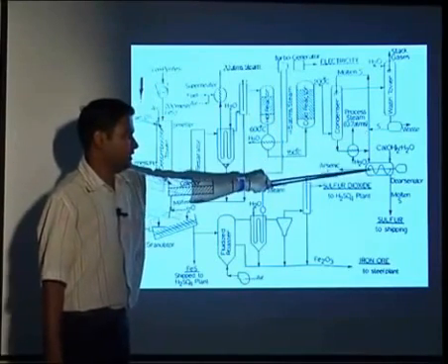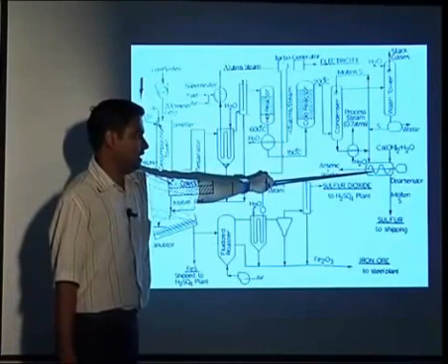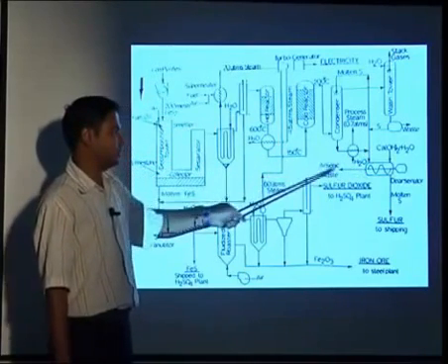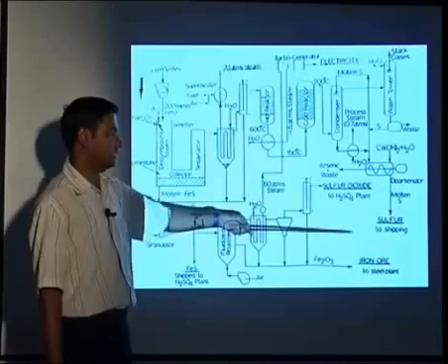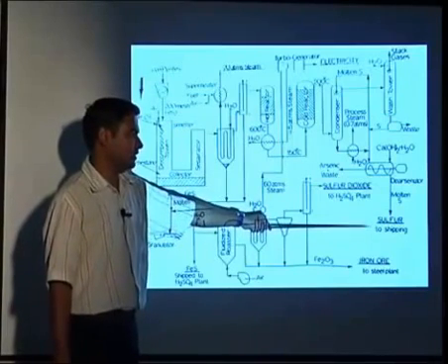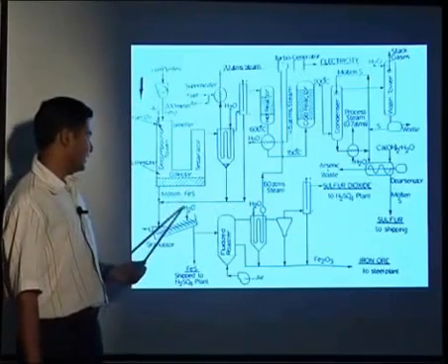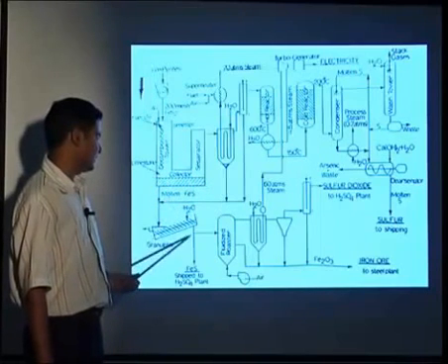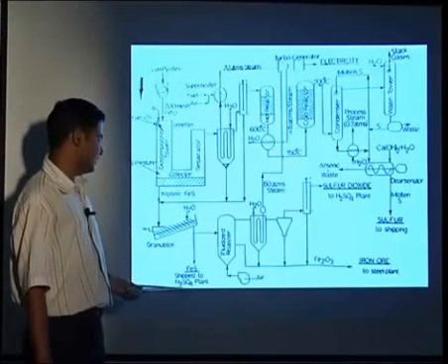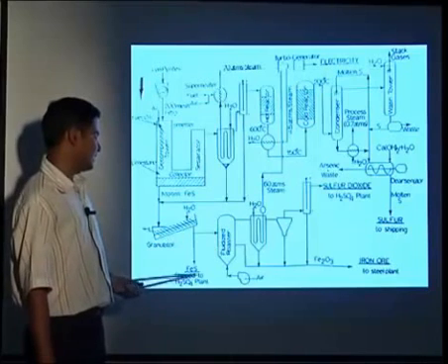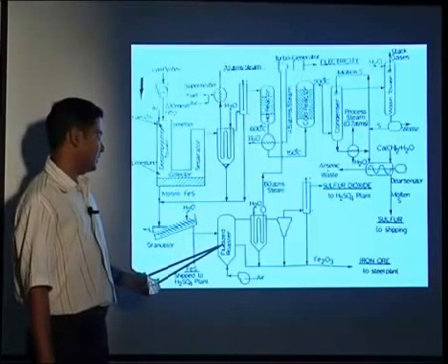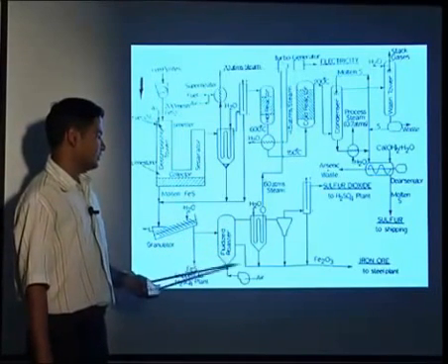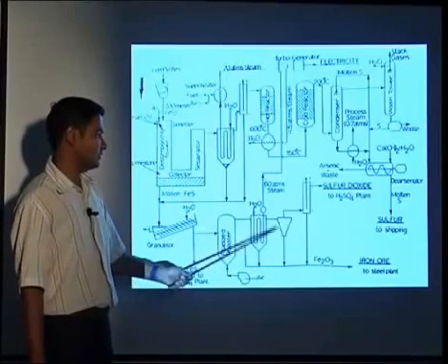So the sulfur here we get, and we are washing with the calcium hydroxide to get rid of the arsenic and waste, and the sulfur we are sending to ship. Then here, after limestone and collecting the impurities, the molten FeS, after solidifying, we are sending to the sulfuric acid plant. And the remaining one in the fluidized roaster will form Fe2O3 and sulfur